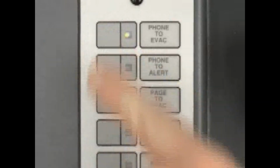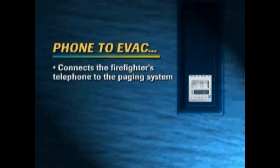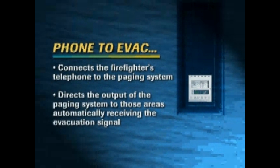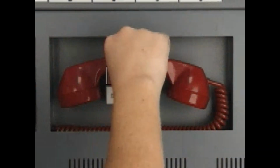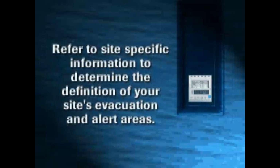The phone-to-evac switch LED is used to connect the firefighter's telephone to the paging system and direct the output of the paging system to those areas in the facility automatically receiving the evacuation signal. The phone system can then be used to page in the evacuation area. Refer to site-specific information to determine the definition of your site's evacuation and alert areas.